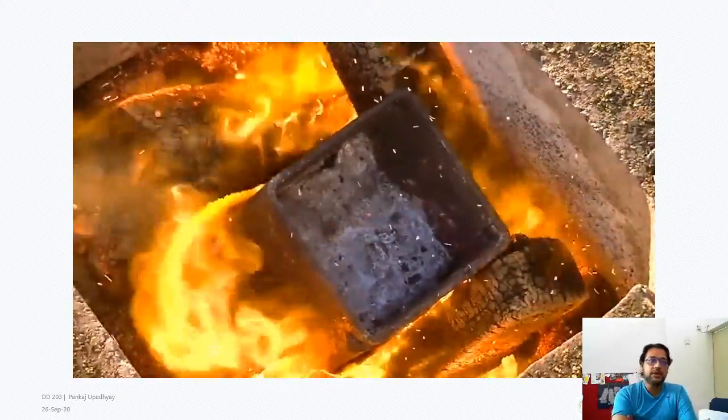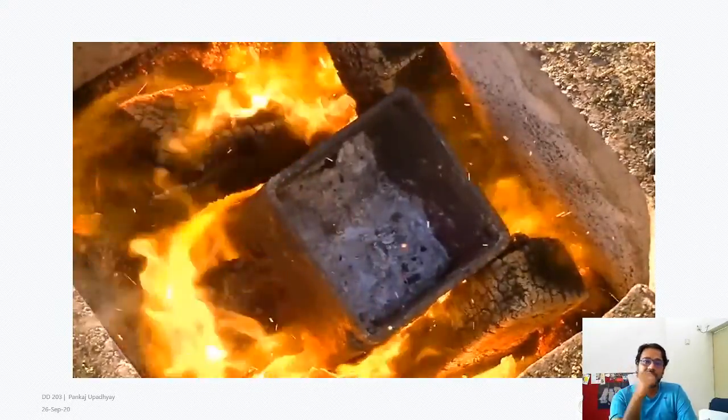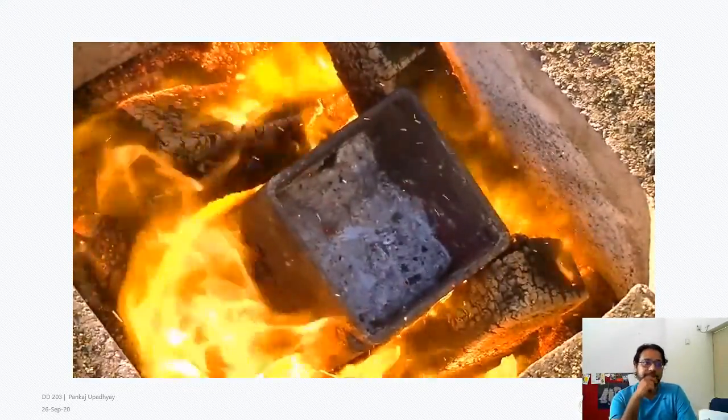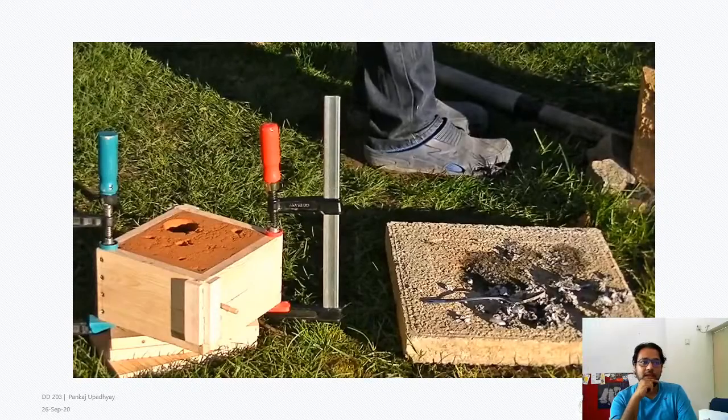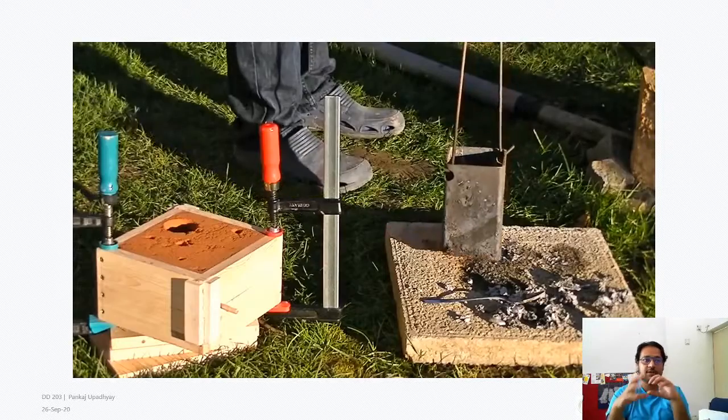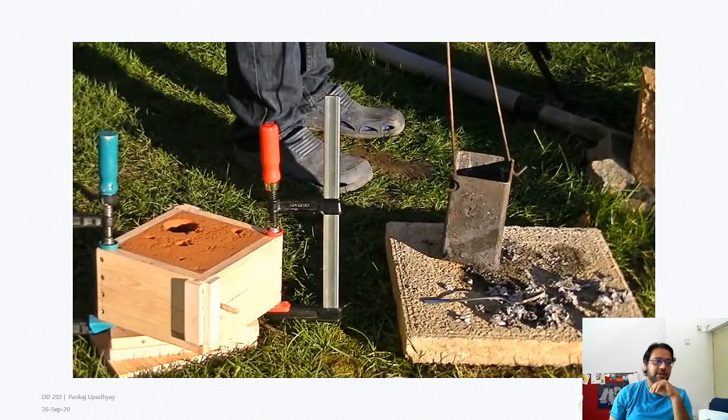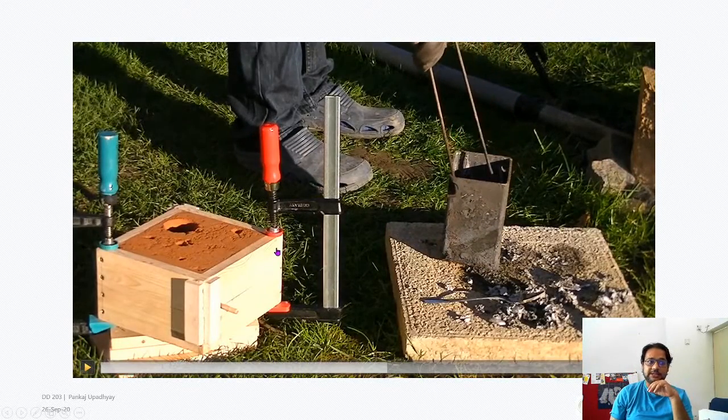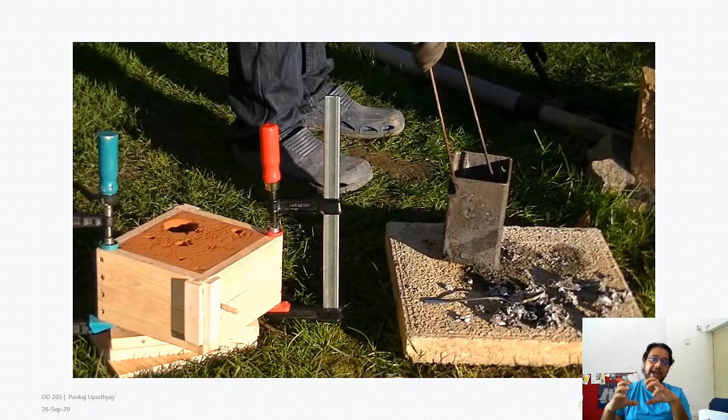Aluminium was molten in a coal fire and then poured into the mold. With steel also. Clamps guaranteed the mold won't open and let the aluminium spill out. So remember, this is one of the very important steps in casting, to ensure that the cope and drag are clamped together quite tightly, enough that the molten material, once it's poured, doesn't flow out of the gaps between the cope and the drag.